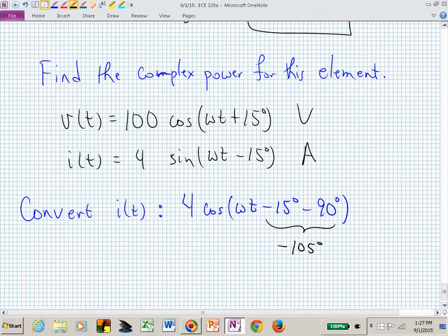These do not have the same phase, they're out of phase. So if you were multiplying these as time domain expressions, your voltage humps and your current humps are going to be shifted in time. And now you can see that the product of I and V is going to have some negative piece, some positive piece, some negative piece, because you're multiplying these as a function of time.